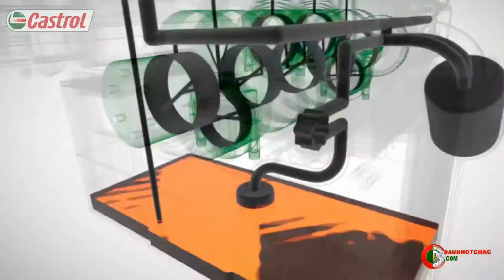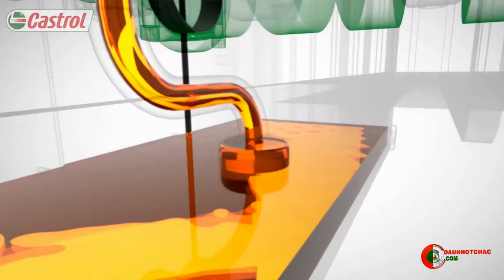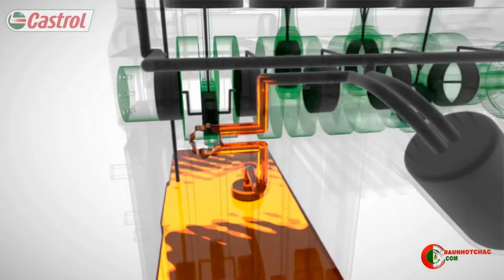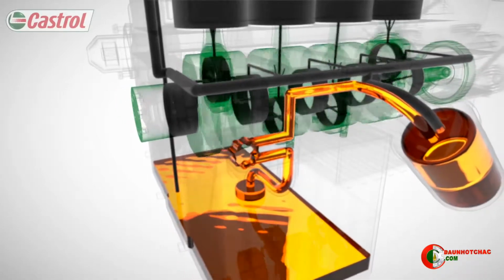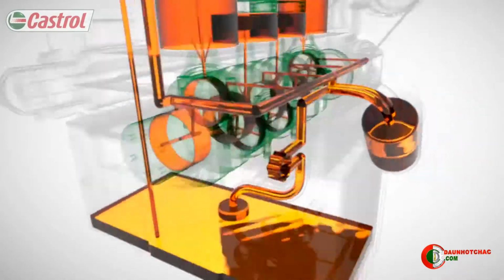The oil pump is vital to the life of the engine. It sucks oil up from the sump through a pickup tube, pressurizes it, and sends it around the entire engine through a circuit of oilways. From the pump, the oil travels to the oil filter, which removes microscopic particles and supplies clean oil to the rest of the engine. Clean oil flows to all the critical engine parts.